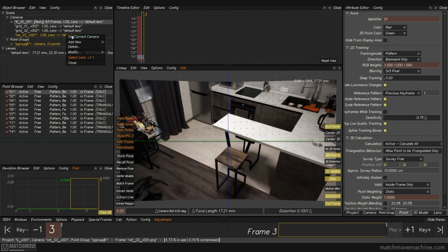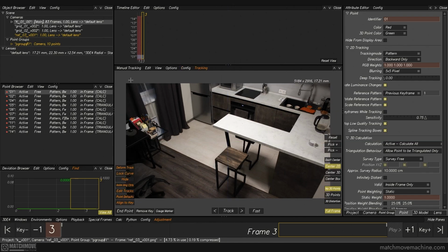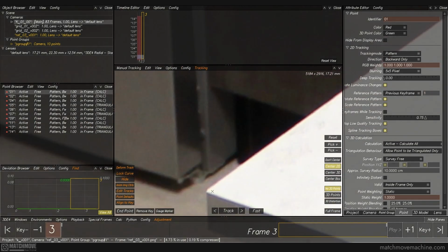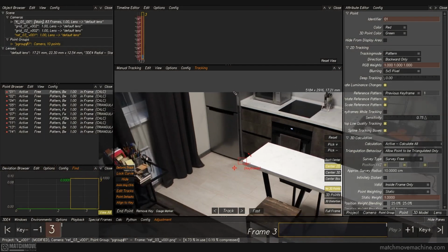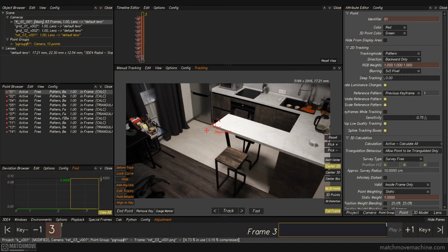Here's an important detail. To switch between cameras without losing the selected point, both clicks really do need to be with the right mouse button. Select the point in the main camera, double right click the reference camera, or right click, switch to this reference camera. The selection stays active. Next, we switch to mono tracking mode and place the point in the same spot on the reference photo. The point is already selected, so we just left click the correct location to create the corresponding key. We repeat this for all other trackers that are visible in the reference frame.